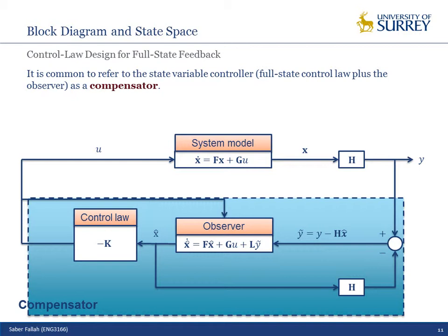Sensors give information to the ECU. Based on the information, you have the control logic, estimator or whatever. The control logic calculates the force. The force goes to the actuator, and the actuator generates the proper force to adjust the performance of your system. For a suspension system, you can have a hydraulic actuator, or an MR damper or ER damper, a semi-active suspension system to control the system.